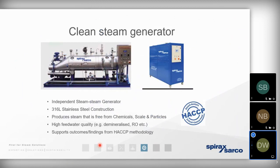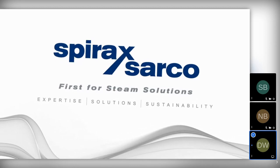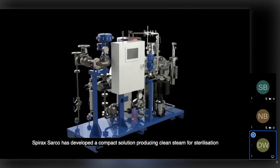So how's that done? Well, typically that's done by using what we refer to as a clean steam generator. Basically, it's a 316 stainless steel steam to steam generator. We use that plant steam that may have some contaminant present within it. And by using a chemical-free source of water and generating steam in a 316 stainless steel generator, we can guarantee that we're providing steam that will hit the defined requirements. So I'm just going to play a little animation now that will hopefully give you an insight with regards to how we can use a clean steam generator to meet the requirements of the vast majority of critical applications.